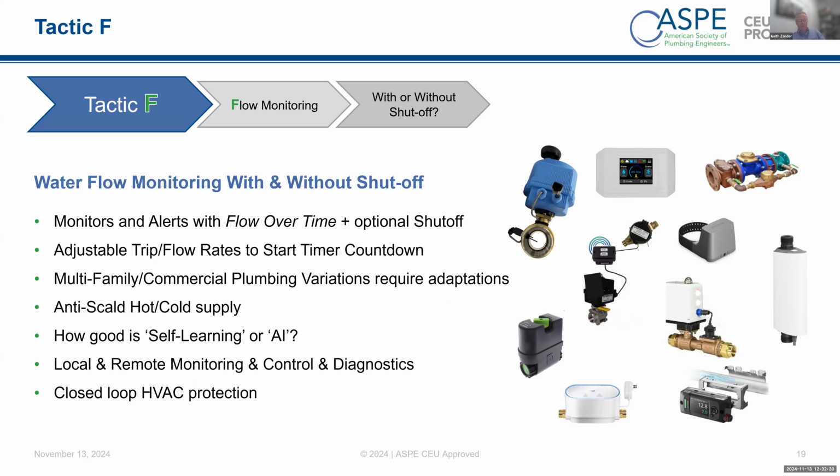Like lower right-hand corner, ultrasonic strap-on. Is it good? It's okay. It gives you kind of a range. Is it real accurate? Nope. Does it stay in calibration? Typically not. Does it require precision installation calibration? Yeah. Do the pads or the gels dry out and need maintenance over time? Yes. Does your pipe change characteristics to make it be out of calibration over time, because you don't have good water conditioning or you get buildup inside the pipe? Yeah. So, pluses and minuses on all this stuff.